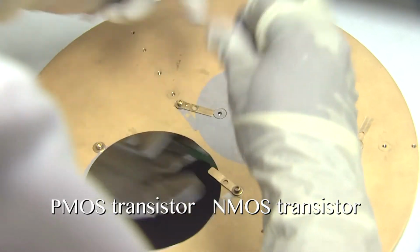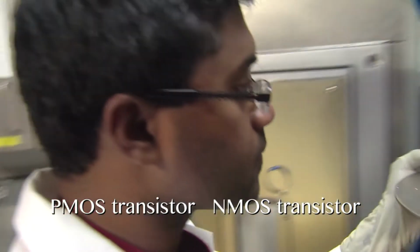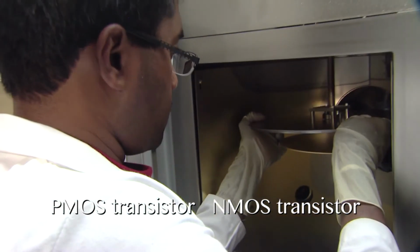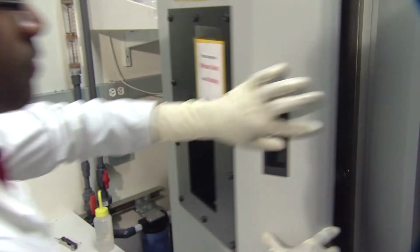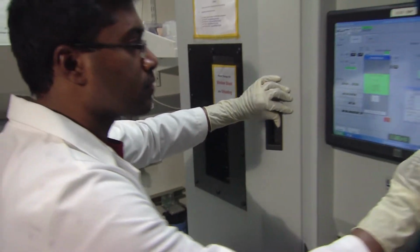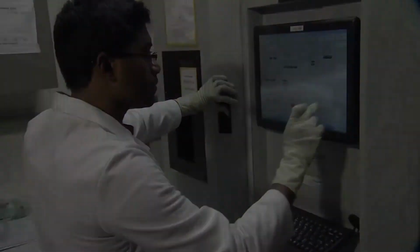Now, it is very easy to realize PMOS transistors with carbon nanotubes, but realizing NMOS transistors is somewhat of a challenge. I'm working on trying to understand the mechanisms behind carbon nanotube doping techniques so that we can realize N-type transistors in future. Hopefully, as we keep on refining the carbon nanotube doping techniques, we can make even better, faster, and more energy-efficient circuits in future.